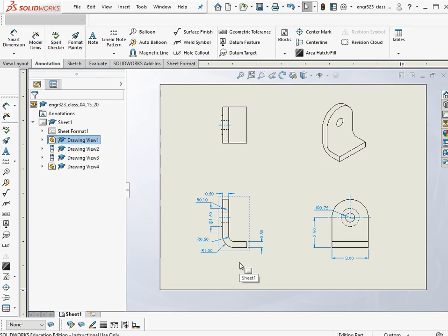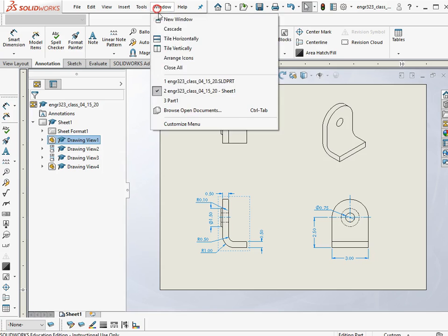Now, there's different ways you could do this. This is not the only way, but it's often easiest, if you have some complicated shape that's been swept or extruded, to start with that face and extrude that, because then you get most of the geometry done immediately.